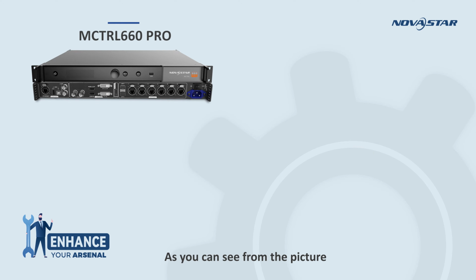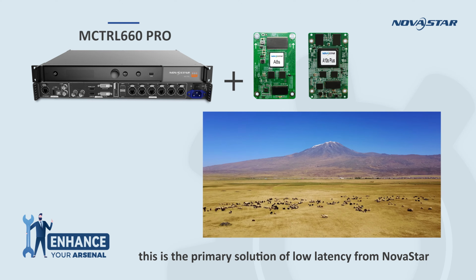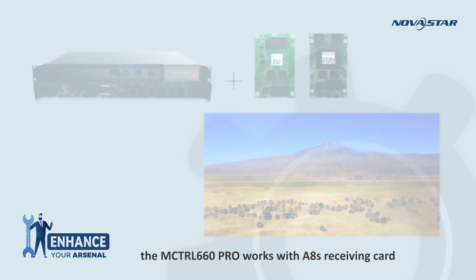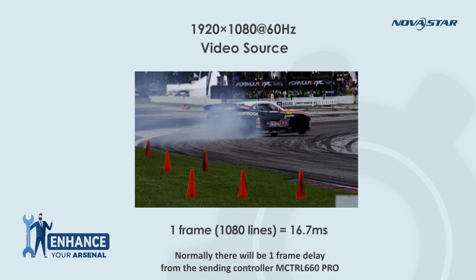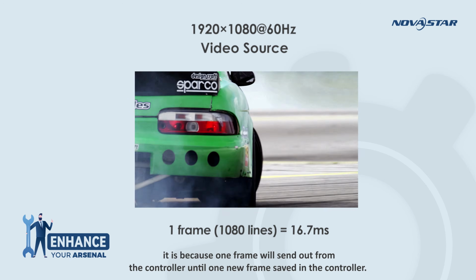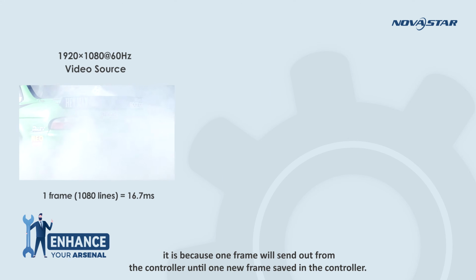As you can see from the picture, this is a primary solution of low latency from NovaStar. The MCTRL660 Pro works with the ATNS receiving card. Let me just explain how it works. Normally, there will be 1 frame delay from the sending controller MCTRL660 Pro. It is because 1 frame will be sent out from the controller only after 1 new frame is saved in the controller.